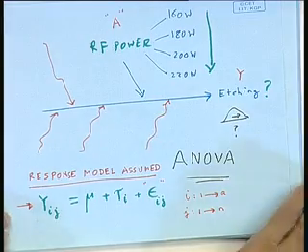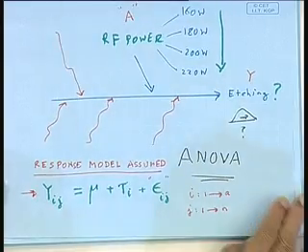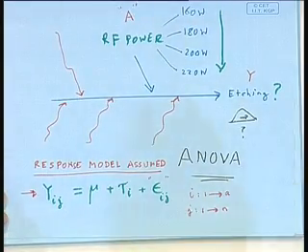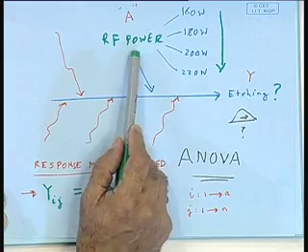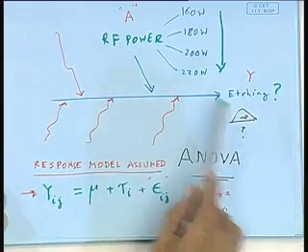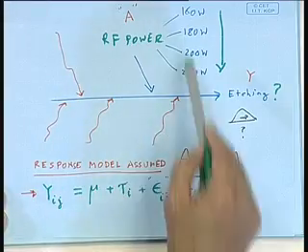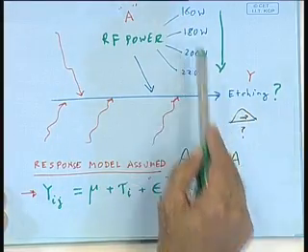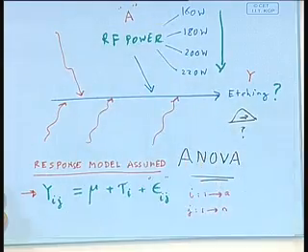Initially, now this is going to be our initial hypothesis, which is just a guess, a speculation. What we are saying is, initially we will assume that this RF power contributes no variation to etching. That's going to be our H0, or the null hypothesis. The alternate, of course, is that at least one of these settings produces a deviation that is different from what is produced by the other effects there.